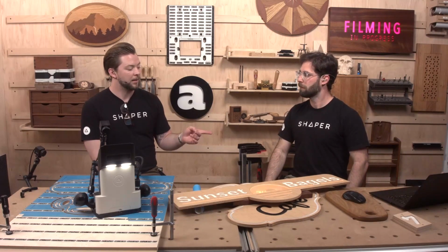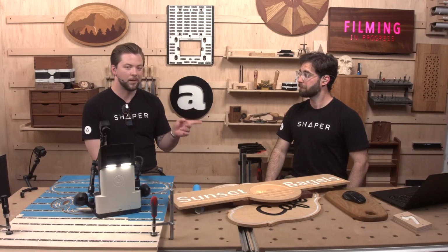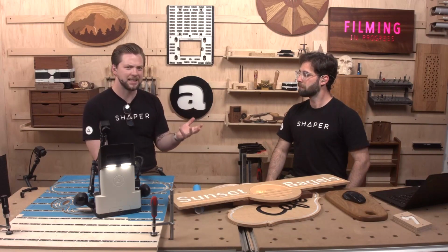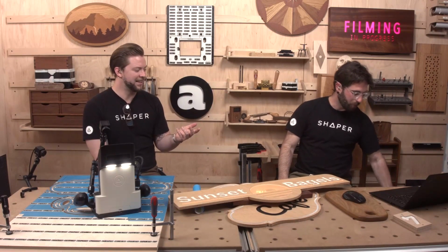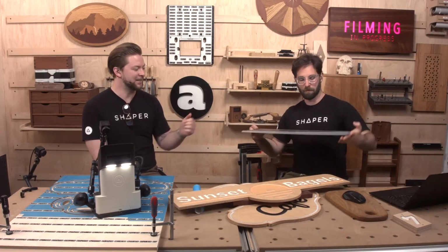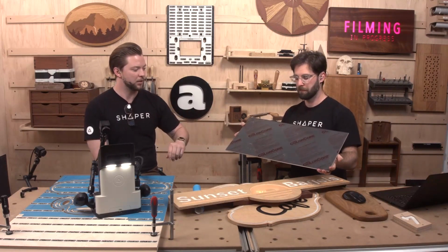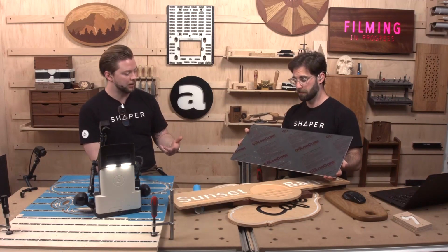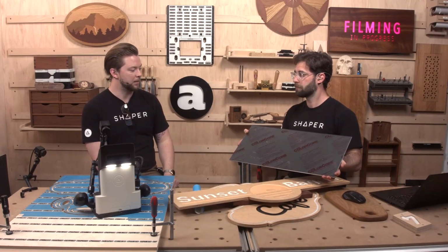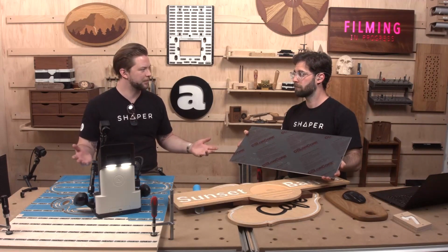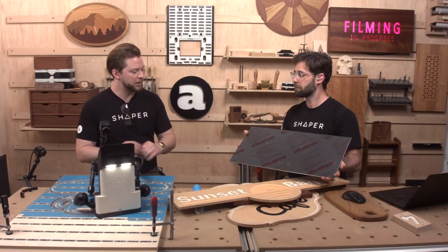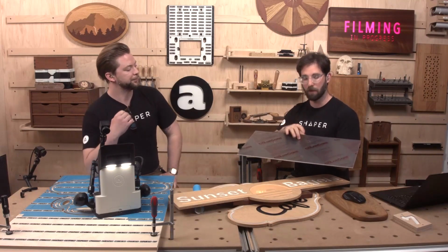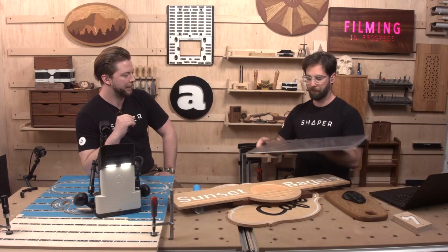A lot of pocketing. Funny thing to note with using HDPE that you'll run into if you want to use it: tape doesn't like to stick to it very well. This is a great pro tip. It'll come with this protective sheet on top. Keep that on while you cut it, because Shaper Tape is going to stick to that better than actual HDPE. If you don't have that, you might have to put a stickier painter's tape or something down in order to get Shaper Tape to stick. Or make a tape board. But if you leave this sheet on, I've had a lot of success with that.